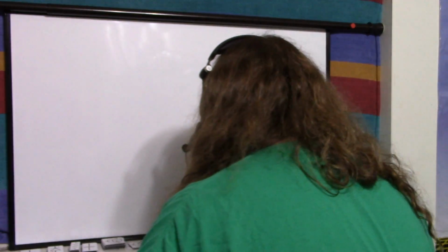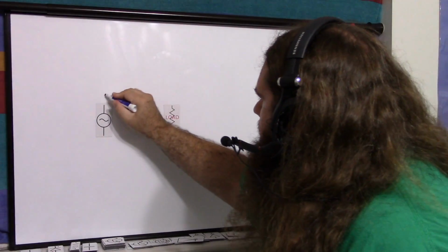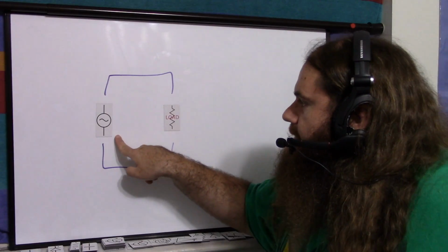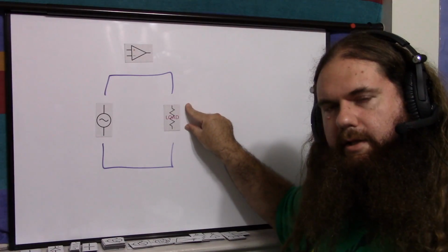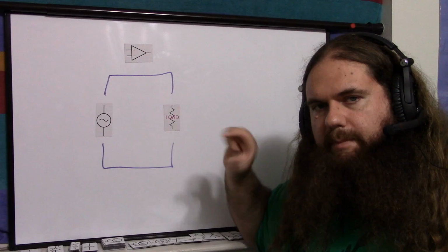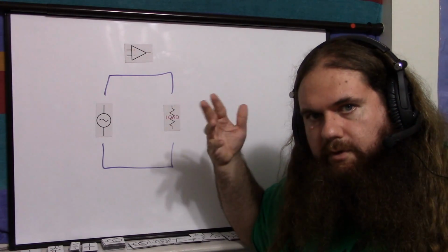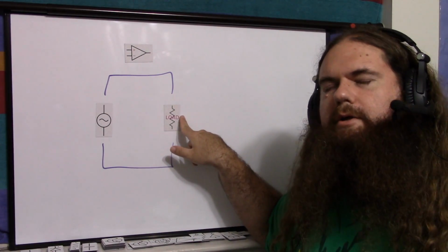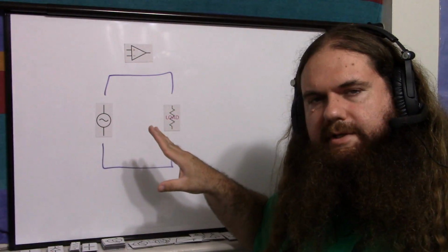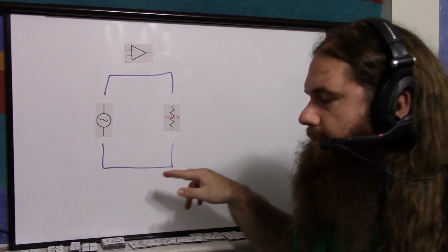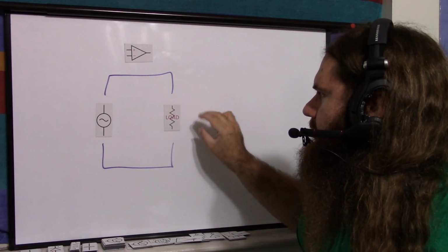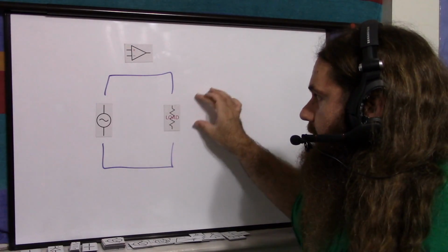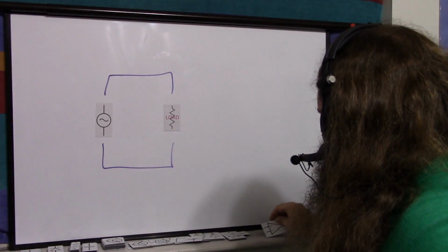Let's say that you have your signal source and you have your load connected together. Your signal is the voltage. The varying current is not a signal. The voltage is the signal. If you have a voltage source, and you change the amount of the load, you're going to get the same voltage. So you can do whatever you want. You can hook this up to a microcontroller pin. You can hook this up to a speaker, assuming your chip is capable of this. You put a power transistor if you need to. But ignoring power requirements, the idea is you can hook up a high impedance, a low impedance, whatever load you want, and the voltage, the signal will stay the same, and it will feed the load properly if it's buffered. If it's not, then it won't.